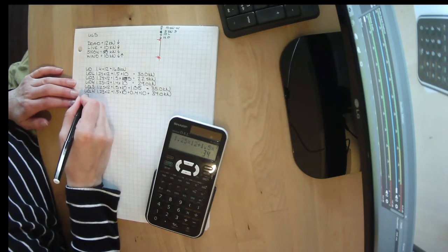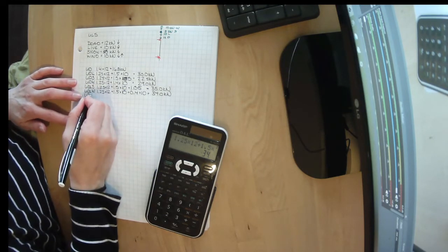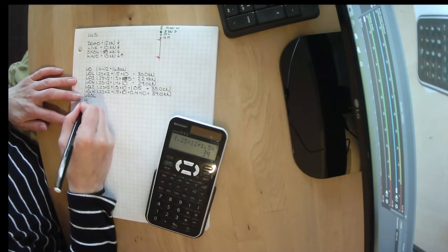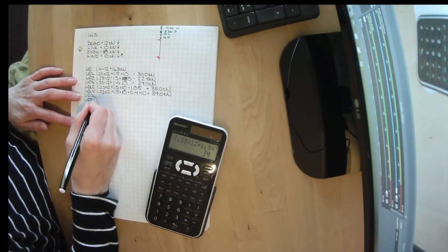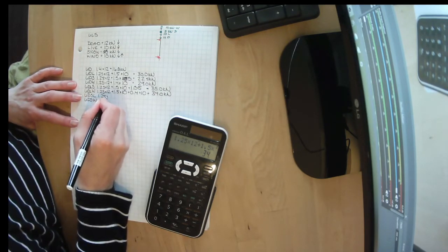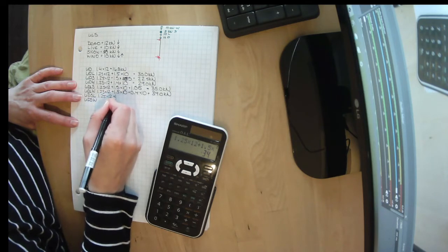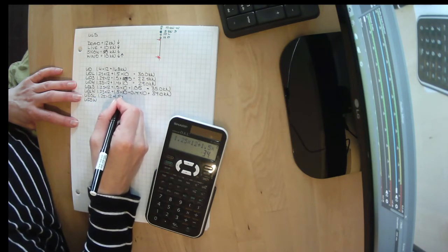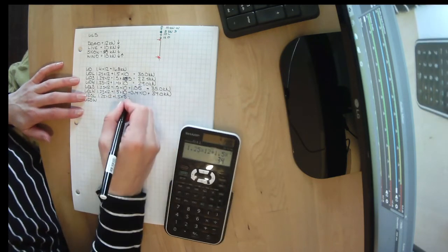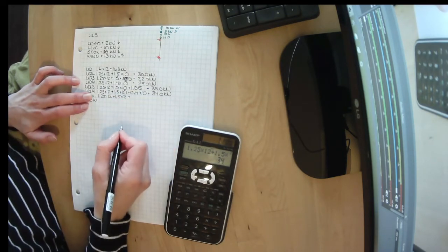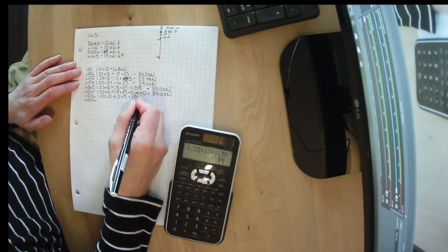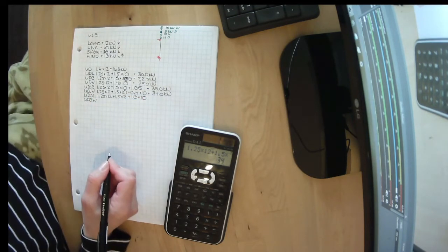So ultimate limit states dead with snow as the principal load and live as a companion, or with wind as a companion. So 1.25 times 12 plus 1.5 times our snow load, which was 5 kilonewtons, plus now live is our companion load, and live we had 10 kilonewtons.